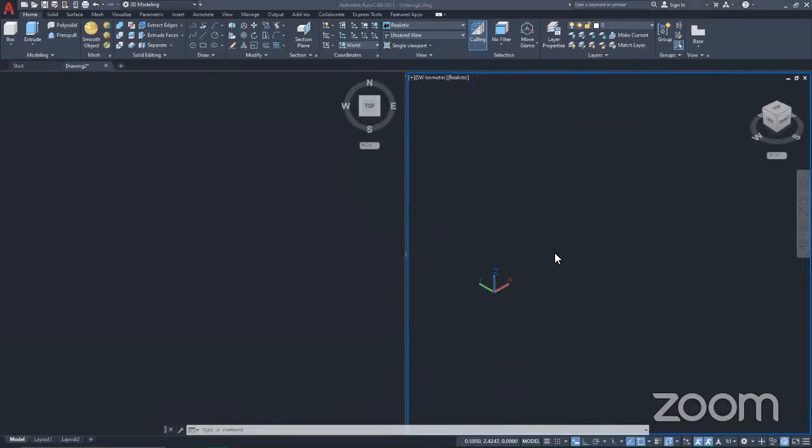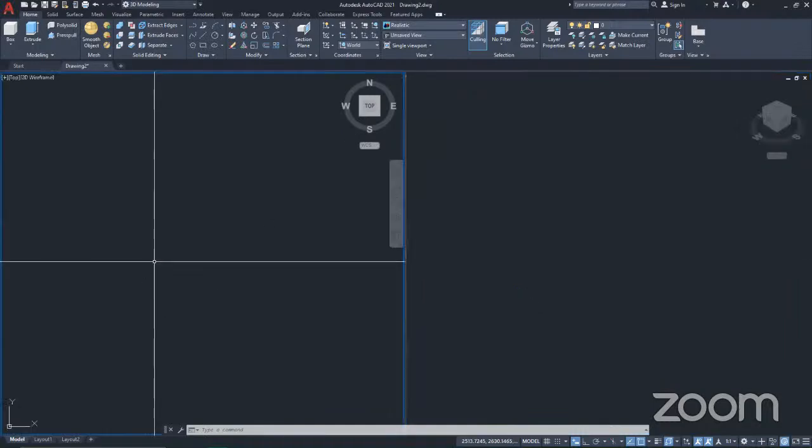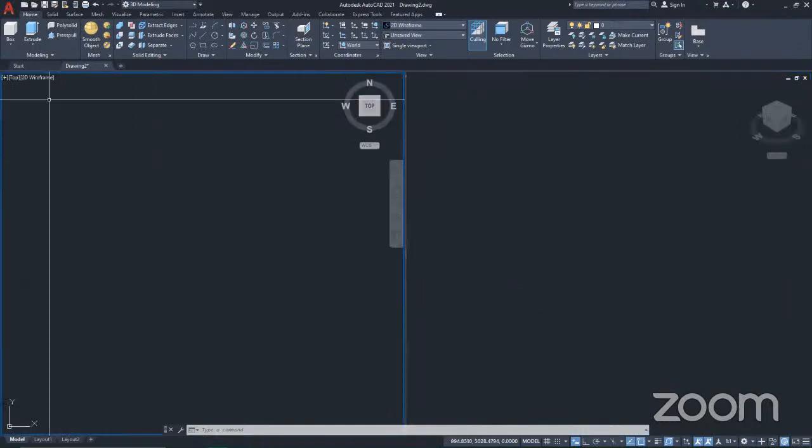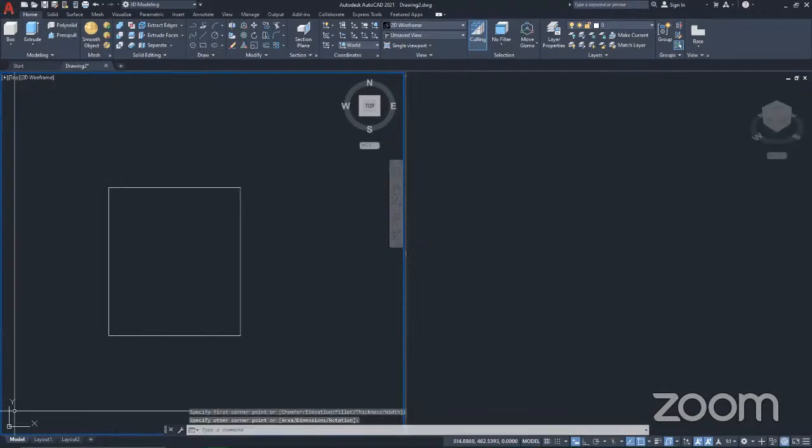And today we're going to be talking about the UCS coordinates, and how to actually make drawings considering the UCS coordinates. If you've noticed before now, when I make my geometries, you see me making them on my XY plane, like you've seen. If you want to know your XY plane, you're viewing from the top. So let's make a drawing. You're viewing from the top, like so. You always draw on the XY plane. Just like you're seeing here, the UCS icon here is showing you the XY plane.